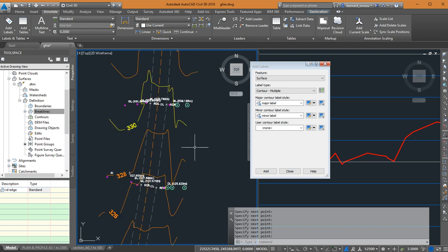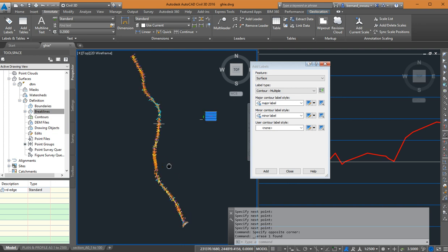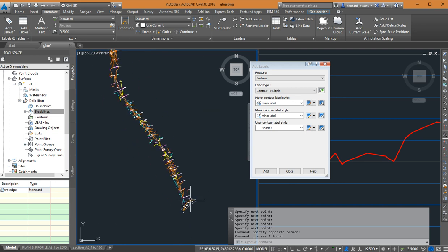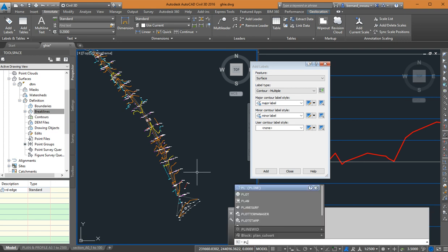So normally what I do is that I will not label it at this stage. I'll wait, do my center line. When I do my center line, I will create a copy of the center line to one side. I'll offset the center line, create a copy of it to one side, and use that to do the annotation from beginning to end. So let's try that one and see. Let's assume what I want you to do is just type PL for polyline. PL, polyline. Just type PL, enter.